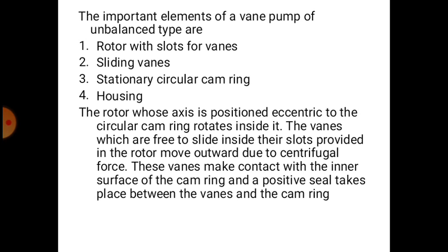These vanes make contact with the inner surface of the cam ring and a positive seal takes place between the vanes and the cam. So when you start the electric motor, the rotor inside the housing will start to rotate, and due to the centrifugal force the vanes come out of the slots and are in contact with the cam ring. For half rotation of the vanes volume goes on increasing and suction is going to take place, and in the other half rotation the vanes are pushed inside the slots by the cam ring and volume goes on decreasing and discharge of the oil is going to take place.